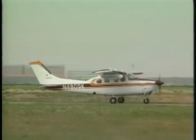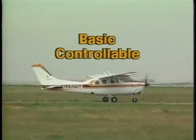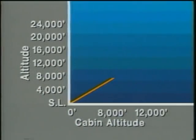There are 2 types of pressurization systems: a basic system and a controllable system. All you have to do with a basic system is turn it on. When the airplane reaches a preset altitude, commonly 8,000 feet, it will begin to pressurize. As the airplane continues to climb, the cabin altitude will remain at 8,000 feet until a second preset altitude is reached. Past this point, which is commonly 20,000 feet, the cabin altitude increases as the airplane climbs.